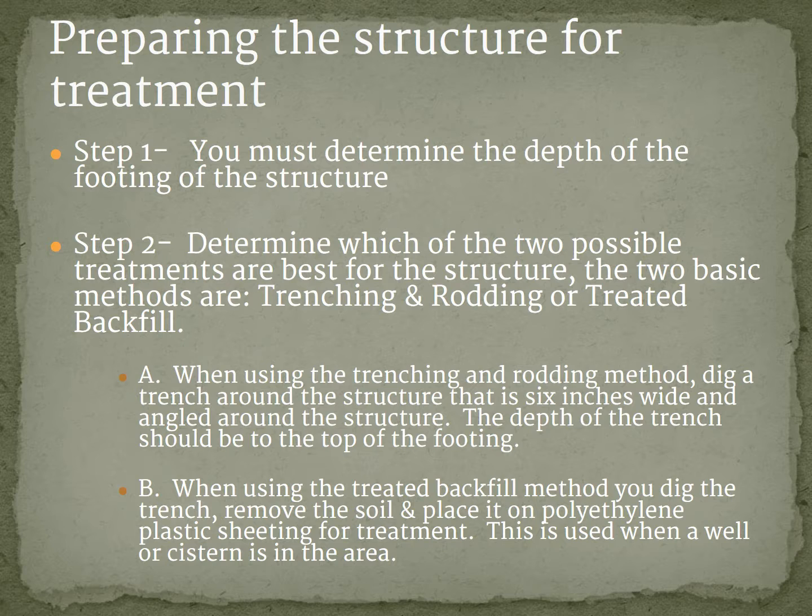So look at the outside grade, look inside your crawl space or basement, and get an idea of where you think that footer is. It's going to be somewhat of a guessing game. You're not always going to know, but keep in mind that as you do the treatment, you're going to treat the trench outside, then push your wand about a foot deep and treat that second level, and so on and so forth, depending on the depth of the footer. So you're going to use your rod, and every 12 inches of depth, you're going to push that rod down and in there. Some of you are going to be in areas where there are basements, and you're going to be doing the 16x10 on a regular basis.